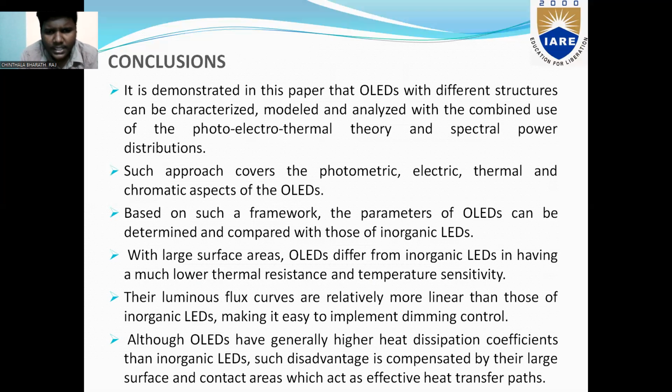With large surface area, OLEDs differ from inorganic LEDs in having lower thermal resistance and temperature sensitivity. Their luminance-flux curves are representatively more linear than those of inorganic LEDs, making it easy to implement timing control.